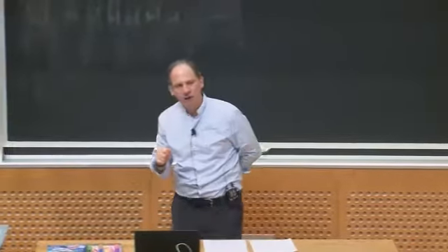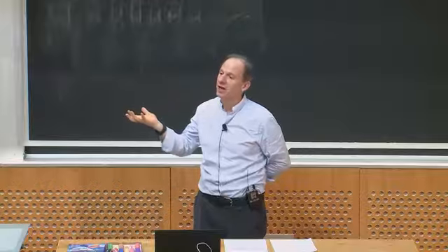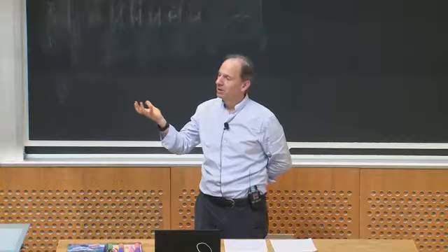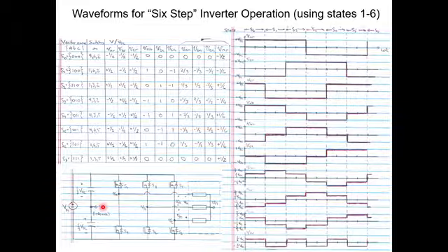That's not the only way you could drive this. You could start thinking about doing things like harmonic elimination waveforms, right? Instead of generating square waves between the top and bottom switching, you could start thinking about putting notches in those waveforms.